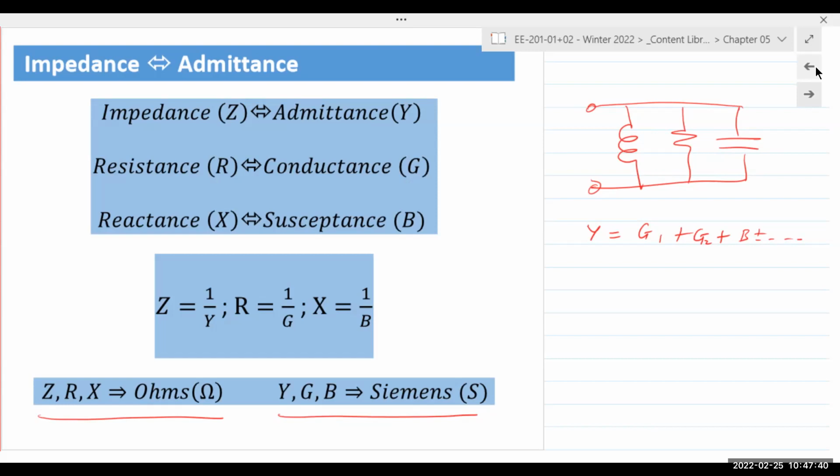So no difference whatsoever. If you apply a voltage to a resistor and an inductor, and you want an AC voltage, for instance, and you want to find the voltage across the inductor itself, you can apply voltage division, or you can calculate Ohm's law, except you are now working with complex numbers. We do not have to write a differential equation. That's the biggest thing.